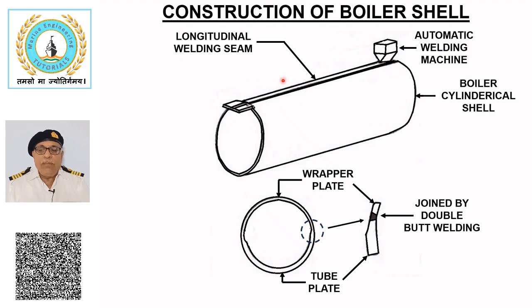The longitudinal seam of the boiler shell are radiographed to detect any defects such as porosity, slag inclusion or cracks, etc. Any defect identified is rectified by grinding and rewelding. The test plate is detached and the disc ends are then welded, following the same procedure. Opening for the manhole and mountings are made and stub pieces are attached to the boiler.